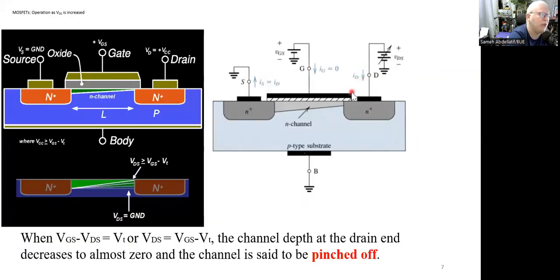A very important and a very critical point: when you reach a certain voltage, we call the saturation voltage, VDS sat, when you reach this voltage here on the drain, a pinch off occurs at this point.